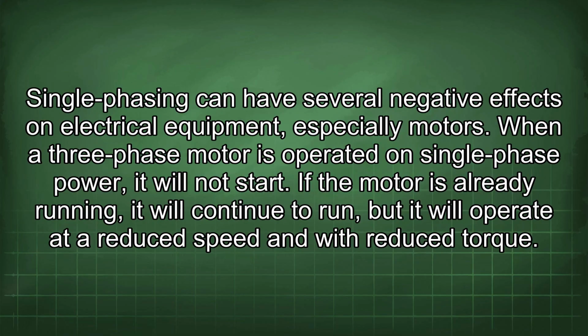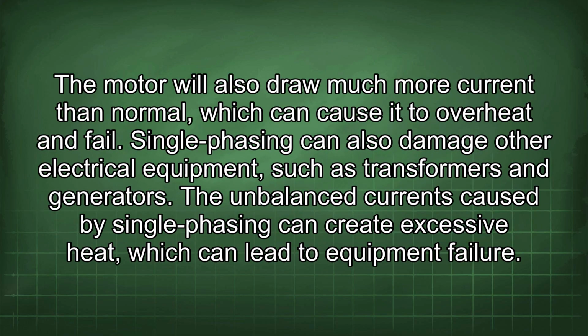Single phasing can have several negative effects on electrical equipment, especially motors. When a three-phase motor is operated on single-phase power, it will not start. If the motor is already running, it will continue to run, but it will operate at a reduced speed and with reduced torque. The motor will also draw much more current than normal, which can cause it to overheat and fail. Single phasing can also damage other electrical equipment, such as transformers and generators.